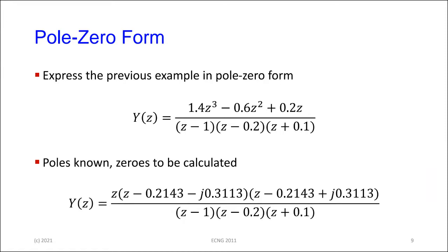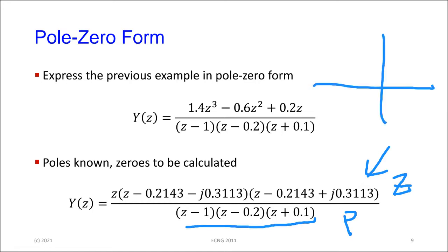So all of these examples now, once you get it into the positive domain, of course, you can factorize, and we have the zeros and the poles, the same thing like in the Laplace transform that we had. And of course, you plot this in the Z plane so you can see where the poles are, where the zeros are, and so on. And we spoke about stability. You're not going to be asked this, but for stability in the discrete time domain, the poles have to be within something called a unit circle.